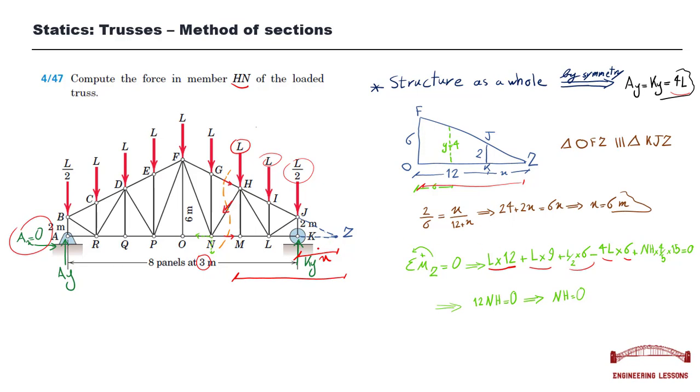Cy is negative because Cy is upward and the moment caused by this force about point Z is clockwise, and we assumed our positive direction is counterclockwise, so we show the direction of this moment by a negative sign. Okay, we wrote all our external forces and our support reaction. Only our unknown is left, to write the moment caused by this unknown about point Z.